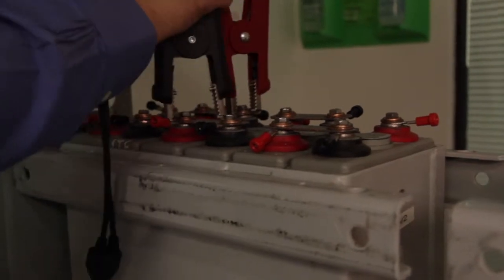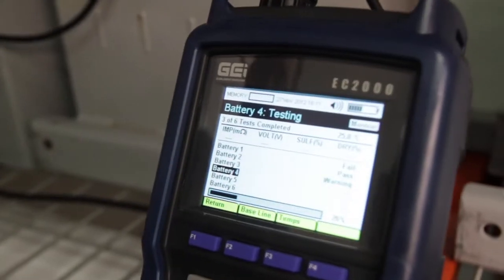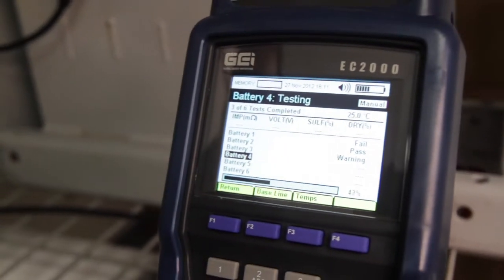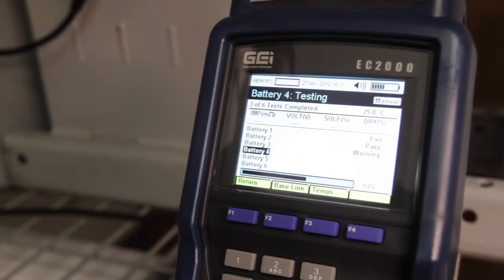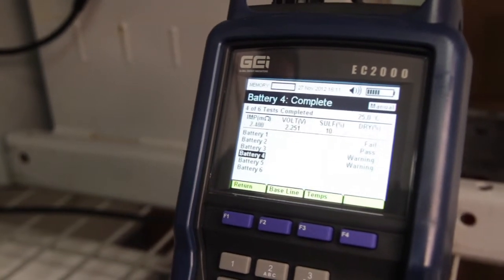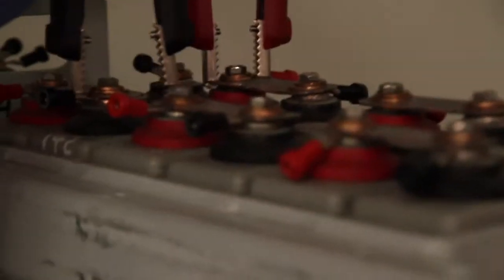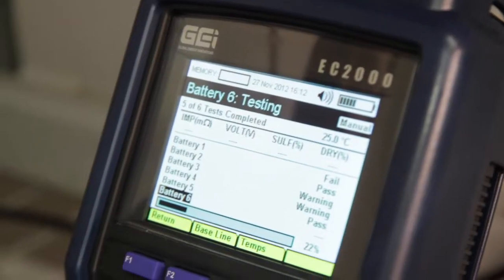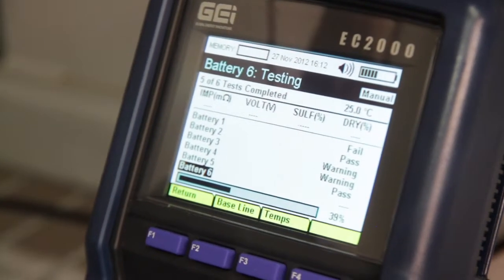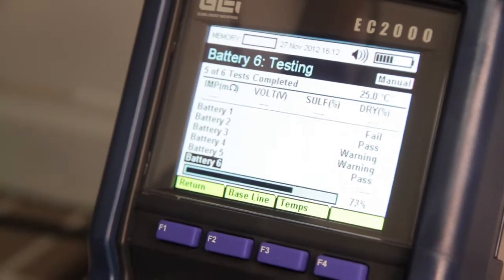Failure to perform reproducible connection, in particular on high-capacity batteries, can lead to noticeable artifacts in the impedance and cell scan readings due to the variable contributions of the post and other conductive elements. Disconnect from the test item once the test is performed and connect to the next one. You can exit the test session at any time by pressing F1. You will be able to resume the test session if the test is incomplete.